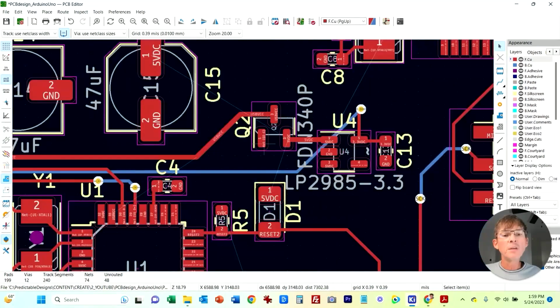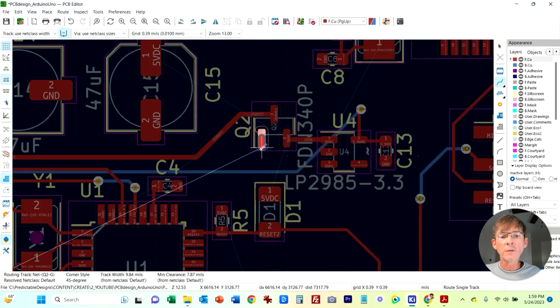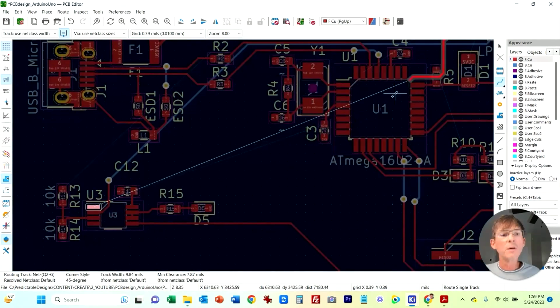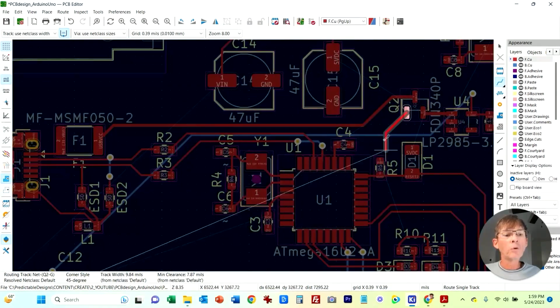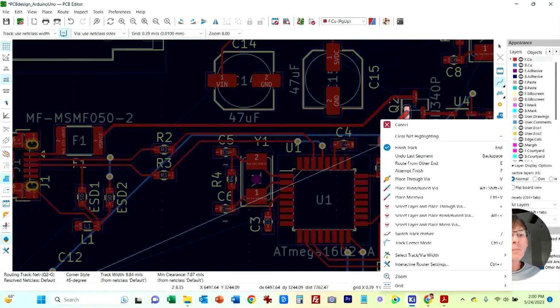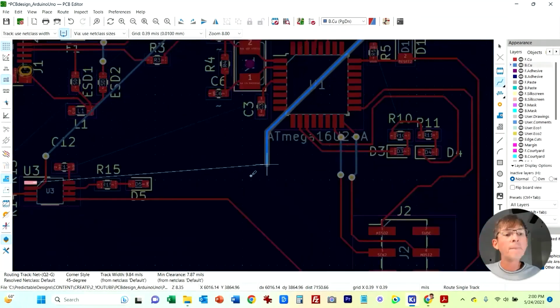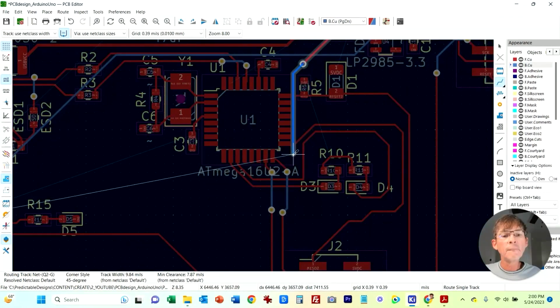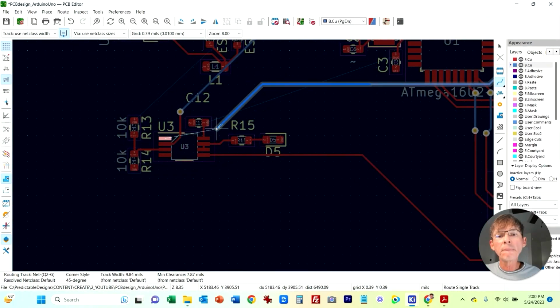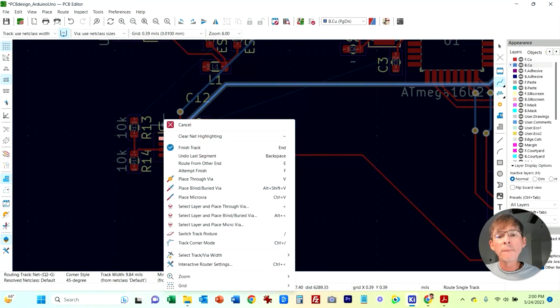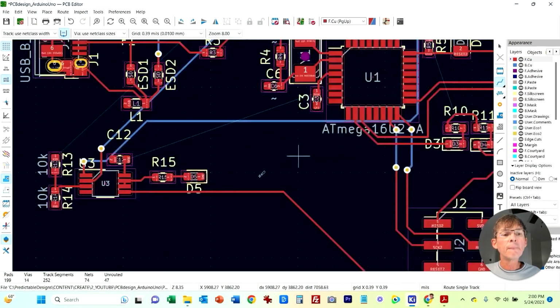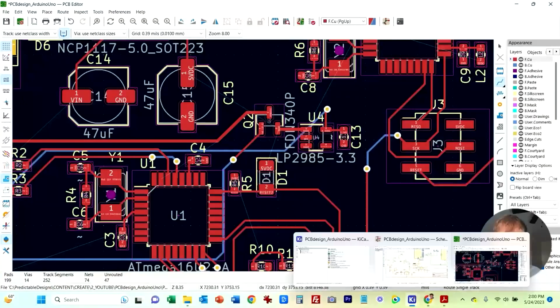And then this is the gate for it, which will come out of one of our comparators down here in the bottom corner. I'm going to go here. So I just do a via there. Okay, there's our gate.